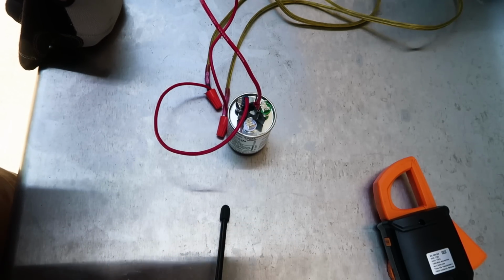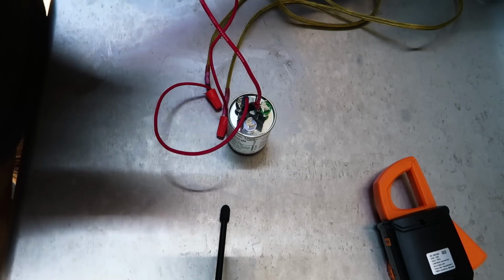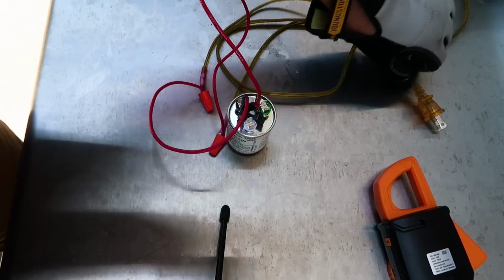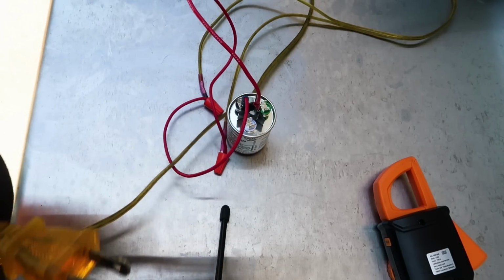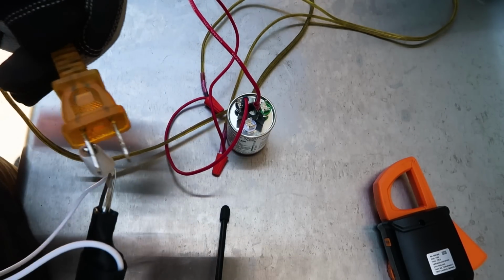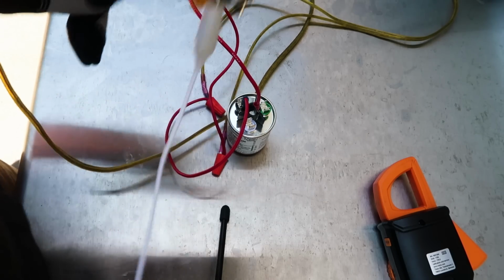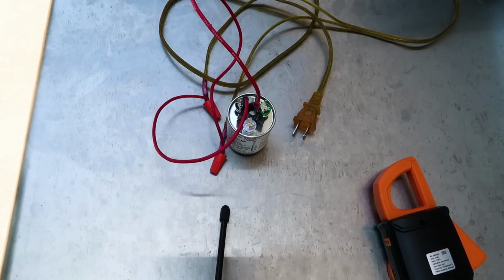Well, first, before we do anything else, I want to show the temperature of this capacitor with it unplugged and then with it plugged in. So you can see we're unplugged here. I'm going to go ahead and discharge the end of this because right now there's actually a charge here. Again, this is the correct way to discharge your capacitor, with the discharge tool, which has a 20,000 ohm 10 watt resistor that I have connected in there. All right, so let's measure the temperature.